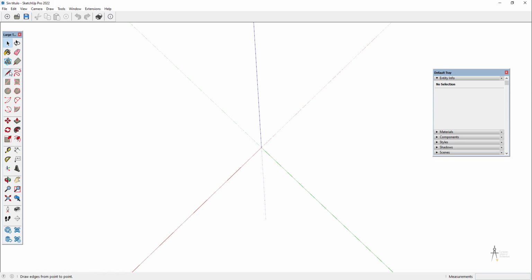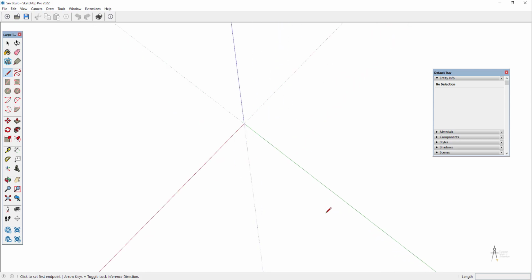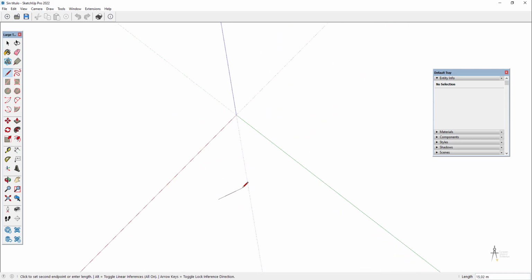So we're going to start with the modeling tools, and it's these ones over here. These are the modeling tools, and we're going to start with a line. So click on this pencil, which is line. Click here, and you can click wherever you like. There you go. As I move around the place where I clicked, you will see that my line turns blue, green, red as I go around.